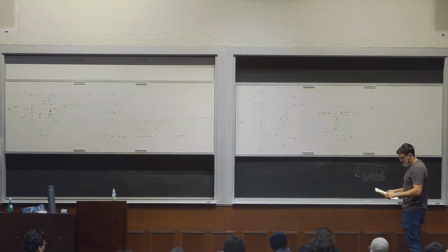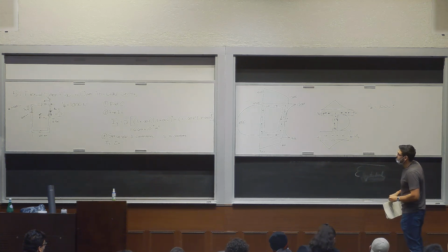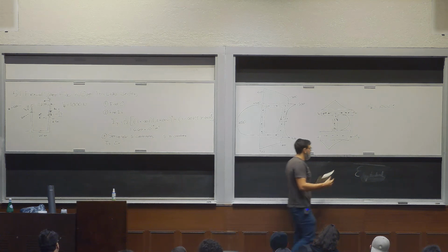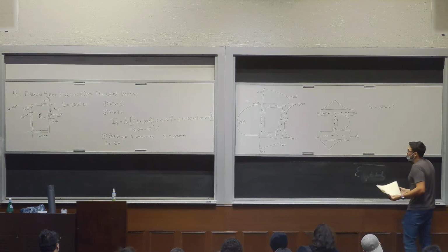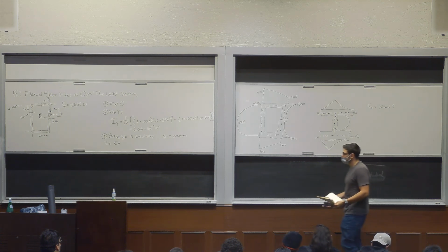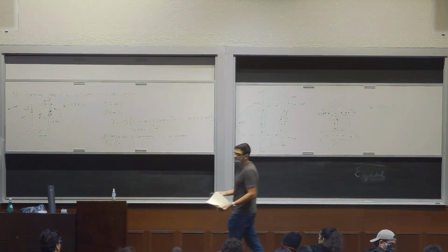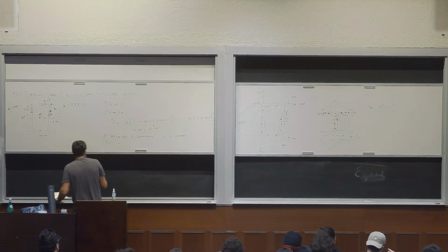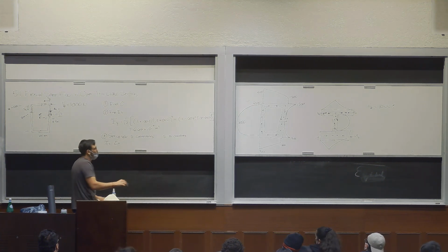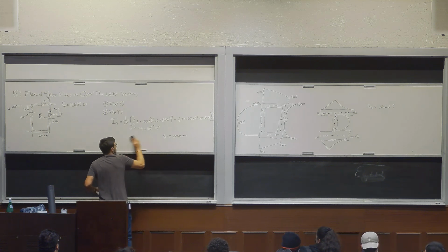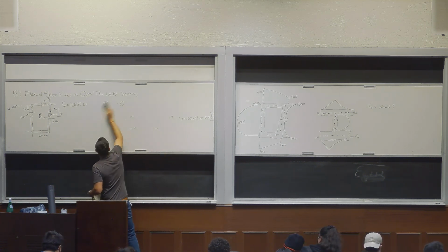All right, now we get a little complicated. So far I think it's been relatively simple. Like I've been saying, I've been describing possibly the simplest case where you have only VZ and you have symmetric sections. So the equations are relatively simple, that VZ times Q over IY. That again is the simplest version. So now I'm going to write the more complicated version, or the more general version, I should say.